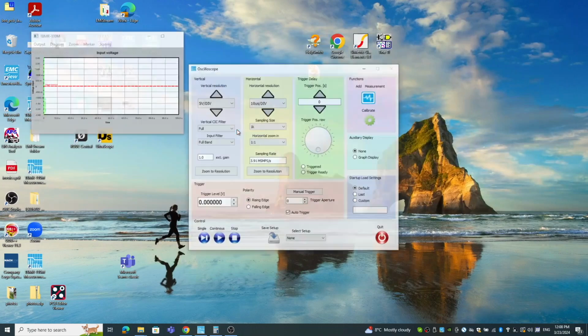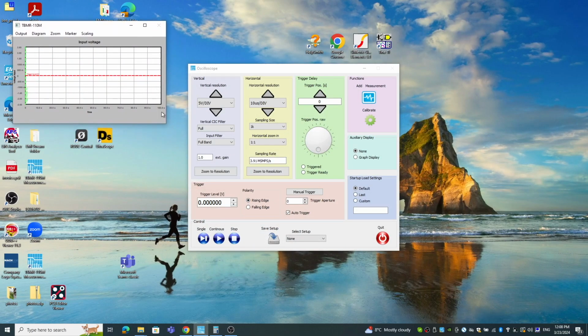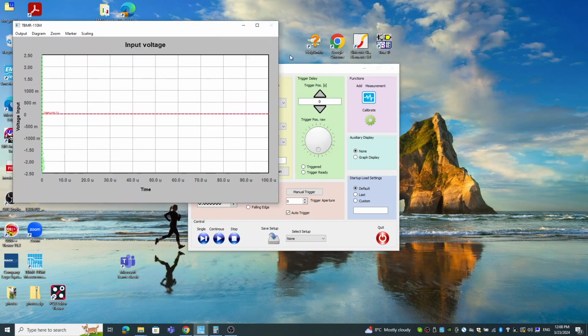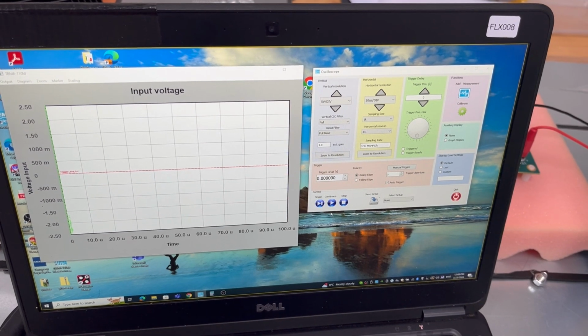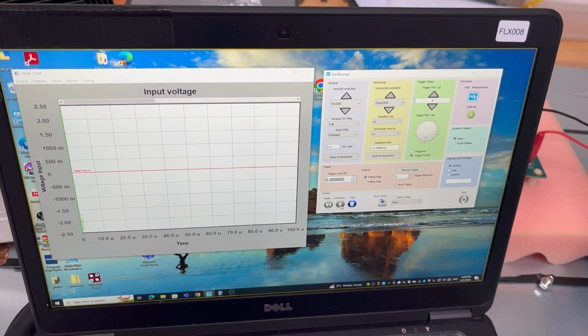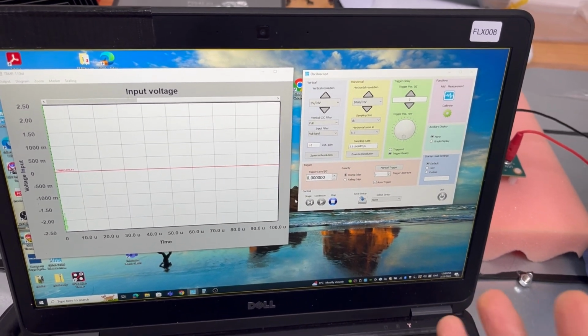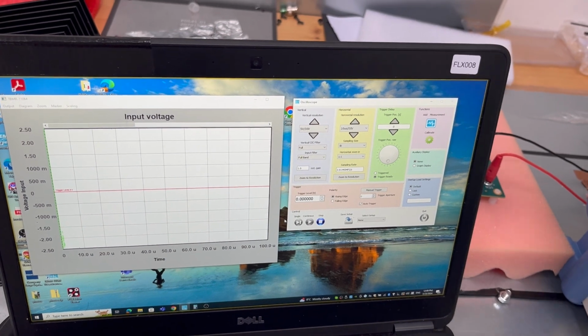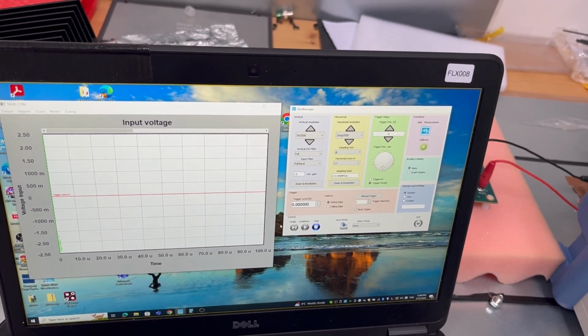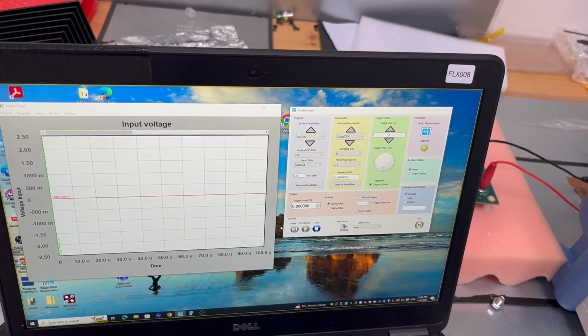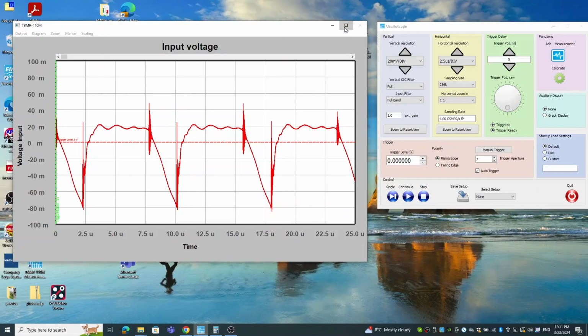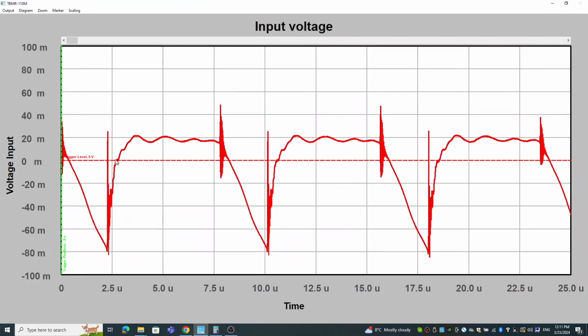Okay, so I'm going to the oscilloscope mode. This is the beauty of this machine. It allows us to analyze a circuit from both the time domain and frequency domain. So let's have a look. If I click continuous, again I'm measuring exactly the same point, which is the LISN receiver, right? So I connect the receiver to the LISN, but rather than looking at the frequency domain, I'm looking at the noise in time domain. So I believe I can zoom in. We understand that if you measure between this point and this point and this point, you will measure probably 130 kilohertz, which represents the switching frequency.